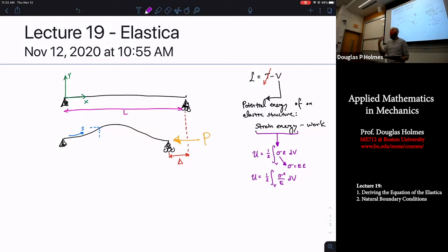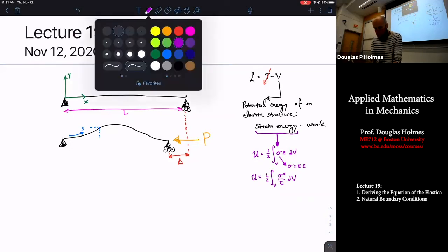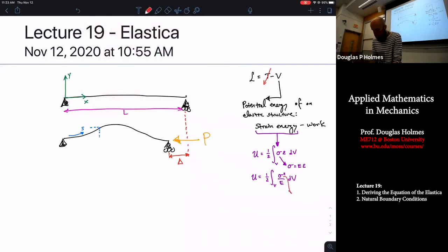The stress is proportional to the moment we're applying times where we are through the thickness of the object over the second moment of area. So dust off the cobwebs, and this should be something like, in bending, My over I.